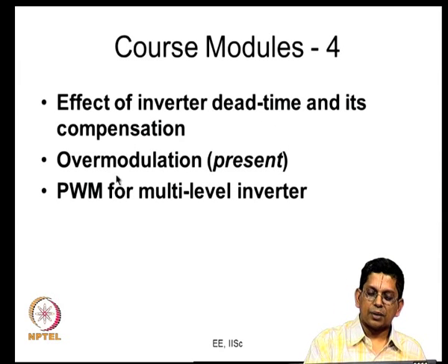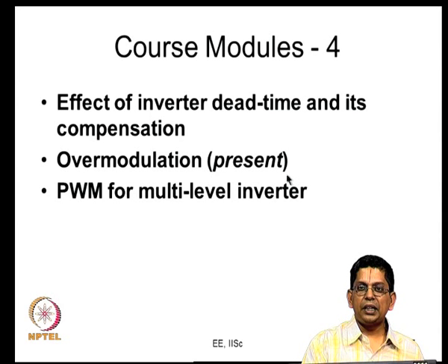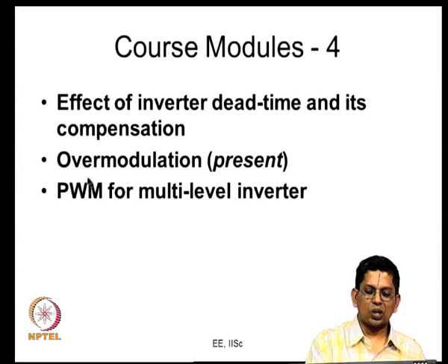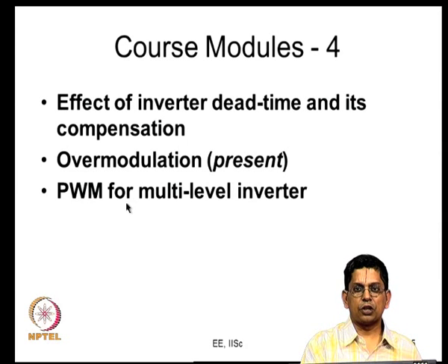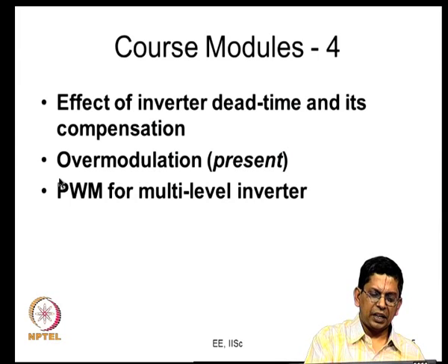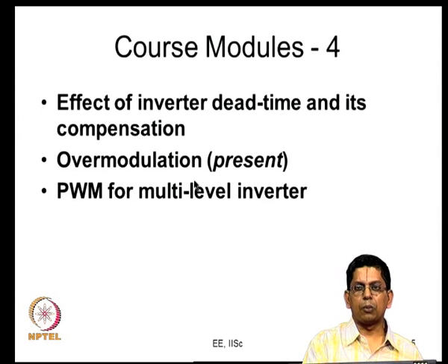Now, we are going to look at something where the ideal fundamental voltage itself is not proportional to your voltage reference. We are going to go into the nonlinear region of operation of PWM rectifiers, where the inverter voltage may not be proportional to the reference. So, why do you have to do that? See, we can trace it back to sine-triangle PWM. Sine-triangle PWM is a very simple way of doing things. You can modulate the AC side voltage with a reasonably good harmonic spectrum.